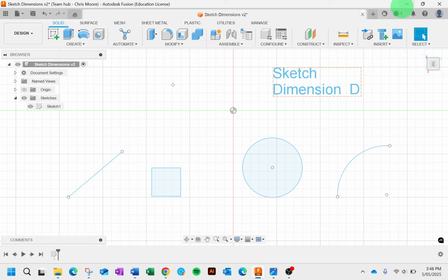Correct dimensioning is essential when designing 3D models for real-world productions like 3D printing or laser cutting. Design should start with accurate measurements, ideally taken with a ruler or calipers to the nearest 1 mil. Tolerance matters, so different materials behave differently.